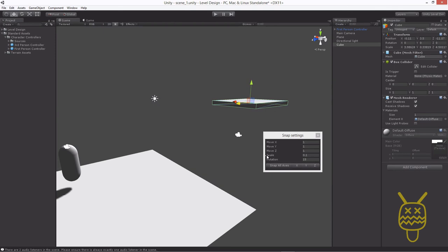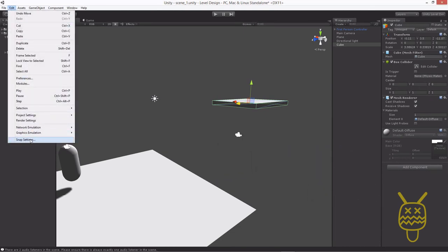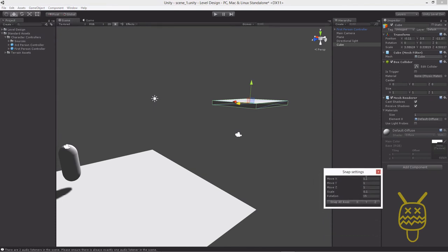You can also place in, for instance, rotation and scale. Rotation does every 15 degrees. Maybe you want it only every 45 degrees. You can change them up and set them however you like with it. Some people use it so often they leave it up. You may find yourself just going to it occasionally and updating a different one depending on what type of movement you're doing. We'll set ours for the moment. I'm going to set it just to the 0.5 and 0.5.